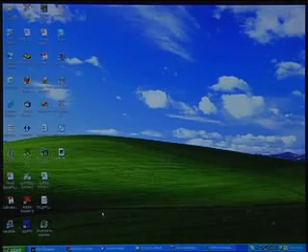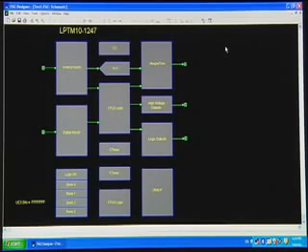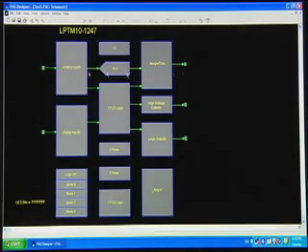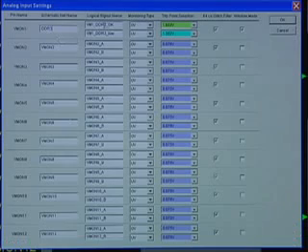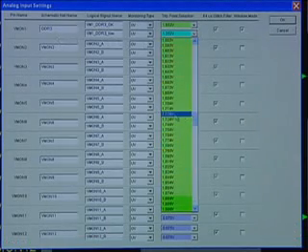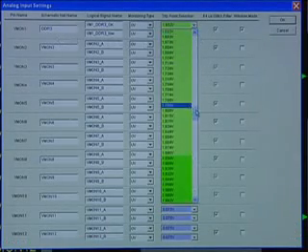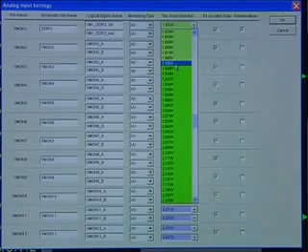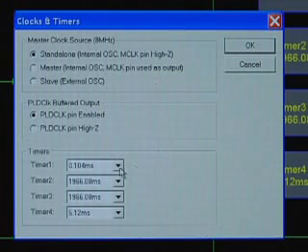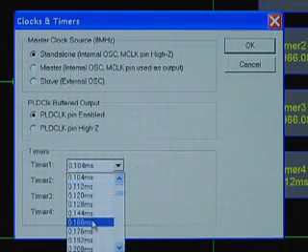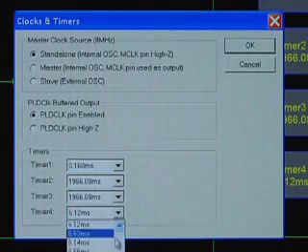The graphical user interface allows you to click on elements of the Platform Manager architecture and adjust design parameters. For example, click on the analog input block, select input 1, and change the voltage to 1.5 volts instead of 1.8 volts to monitor a DDR3 supply instead of a DDR2 supply. No need to change any external component. You can also change other device parameters like reset pulse width and watchdog timer delay in software instead of changing external resistors and capacitors.